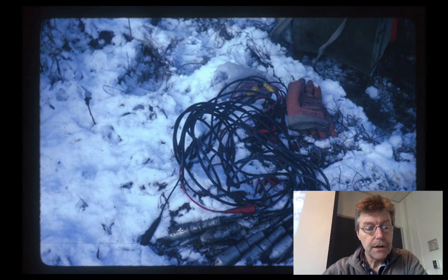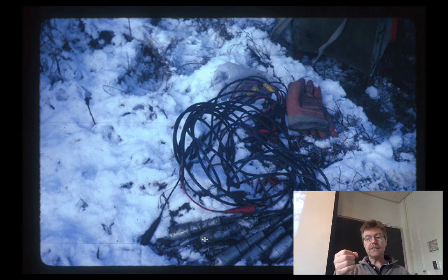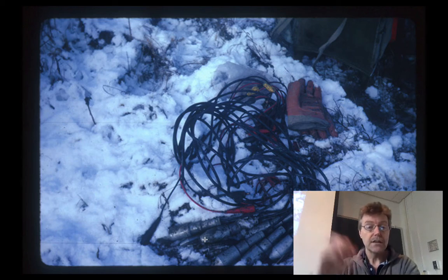So these little conical things are physically pushed into the ground. All it is, is a magnet that sits inside a cage. And when the ground moves by the first arrival, the magnet in the middle, by its inertia, tends to stay still while the cage rotates or jiggles around it. And as it jiggles around it, by Maxwell's principle, a magnet moving in a magnetic field creates a current, and that current is just the pulse that's recorded and sent back to the seismograph.